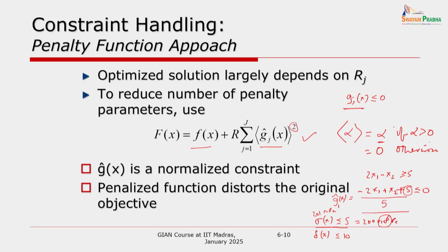So you violated the constraint by 1 million Pascal. On the other hand, for this one, if you violate, maybe it's 10.5, and that's a violation by only 0.5. So there is a mismatch. Here it's a million, here it's only 0.5. If you just use these as G, this is going to be ignored because it's such a small number compared to the other.